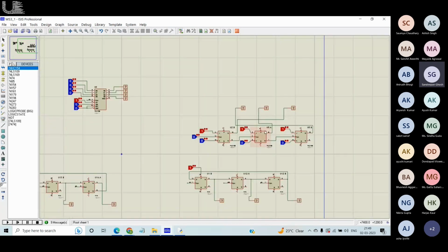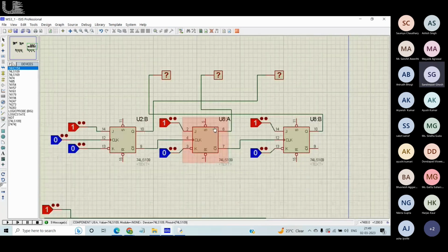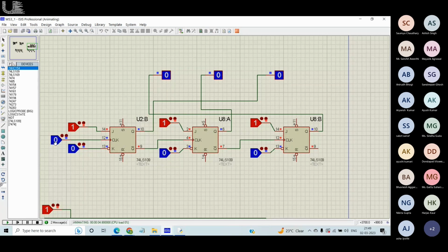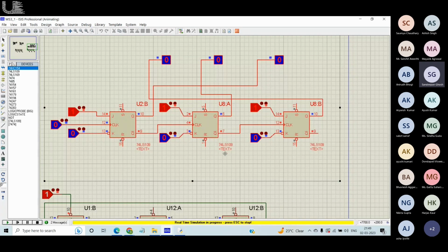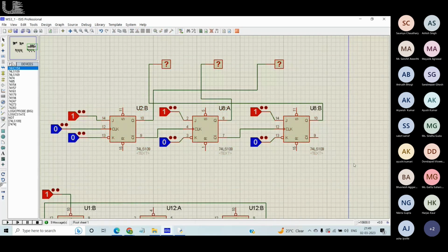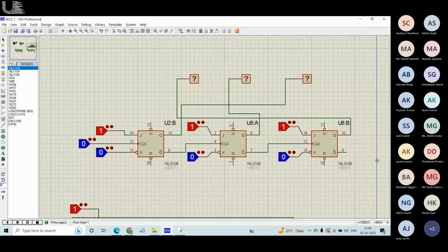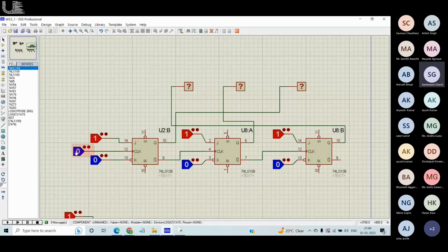And now coming to the asynchronous counters, I've just drawn it out for you to have an idea. I'll just show what it does first. You look at the outputs. This is my input. For an asynchronous counter, as you remember, there was no clock. So to trigger it, I have to keep on pressing this button. If I press this button, I get 1.